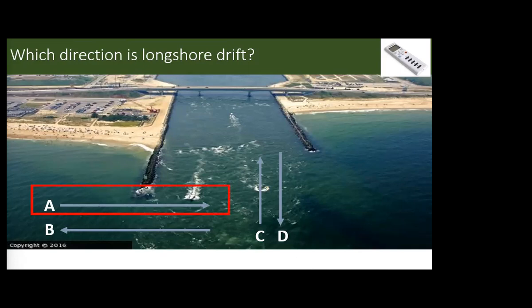Remember, that jetty goes all the way back to, you see where that channel kind of narrows into a bottleneck? That's the start of the jetty. So we have a longer jetty on this side. We have that buildup of sediment over here. So that's where the longshore current is coming from. It's going in this direction. All that sediment is coming from over here, hitting that jetty and getting deposited. Because of that, we're getting erosion on the other side.